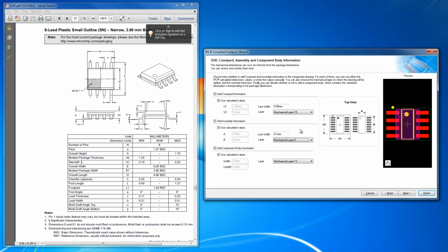If you are working with someone who's using a very old version of Altium Designer, you want to be aware of the fact that any layers, in particular layers 17 through 32, if you're using an older version of it, they're just going to dump it on layer 16. So you may want to try to stay to the first 16 layers if you're working with anybody who's using an older version of the tool. Otherwise you're going to have some problems with it. But I think that as time has gone on and most people have upgraded to the latest tools, that's probably becoming less and less of an issue.